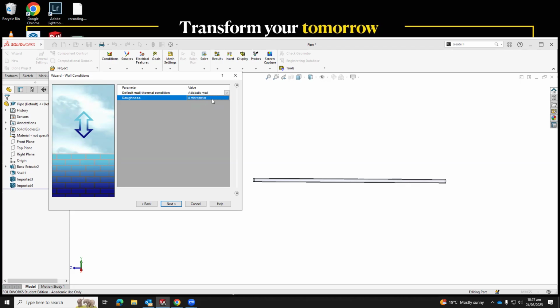Micrometer, that's very important. That is the roughness. So you remember when you used to work with Reynolds numbers to go and work with the Moody chart? We need to know if this is a plastic or a galvanized iron or a steel or whatever. The inside of the pipe, if it's smooth, you get the value, whatever it is. So I would choose something like 0.04. Let's say it's not really a new pipe and has some relative roughness. Okay, next.